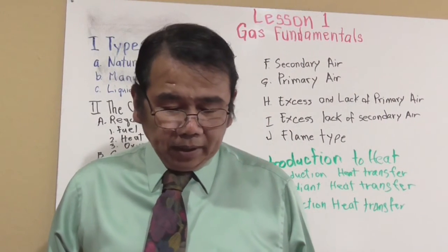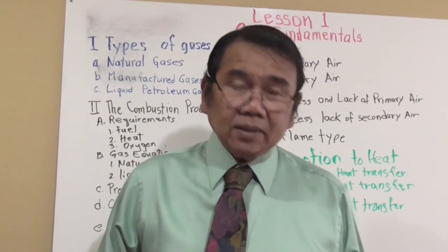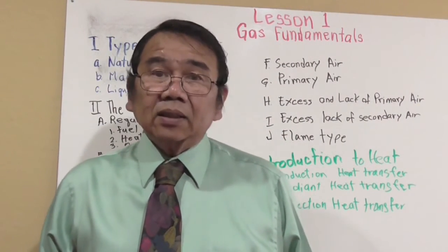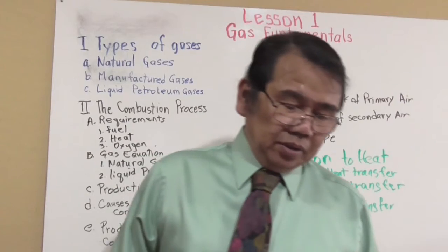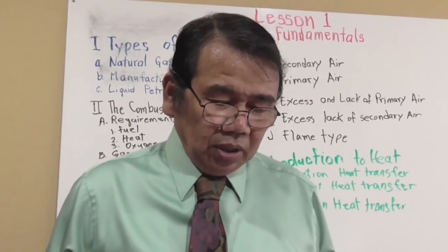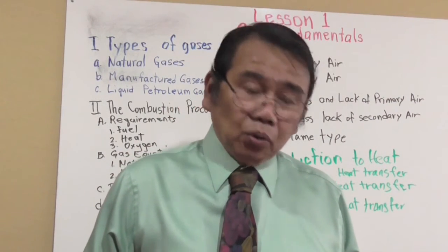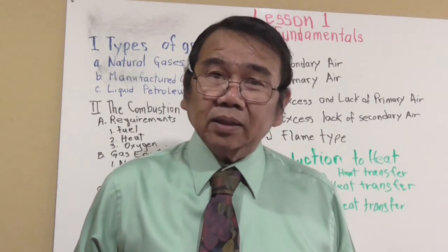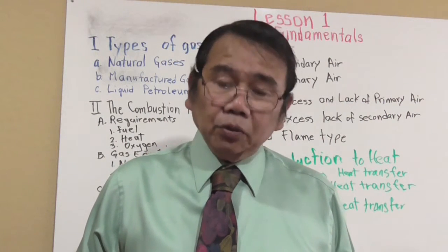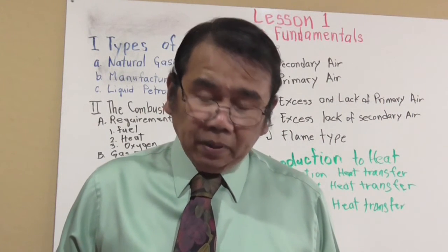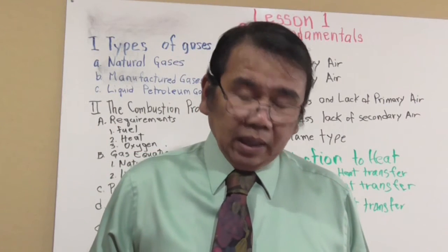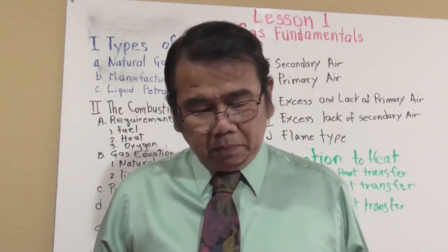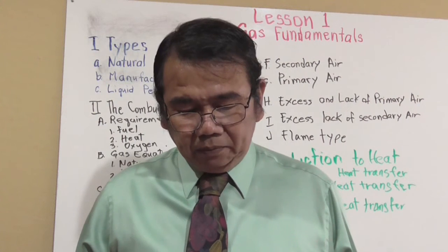And if complete combustion has taken place, the products of combustion for LPG will be 2 cubic feet of carbon dioxide, that's CO2, 3 cubic feet of water vapor, that's H2O, and approximately 14 cubic feet of nitrogen.